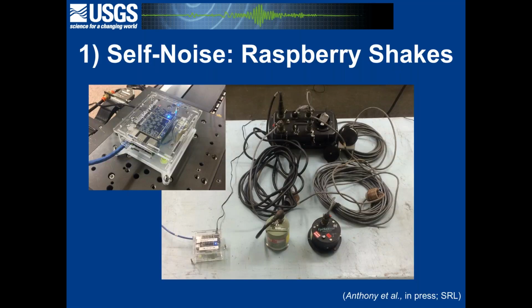Okay, so let's do a quick example of this. I've been thinking about Raspberry Shake seismometers a lot lately, and this right here is a Raspberry Shake. It's a relatively low-cost sensor. This costs about between $500 to $1,000, depending on how you option it. And it consists of a vertical component geophone here, a 3-component MEMS accelerometer, and an integrated digitizer that uses SeedLink. This uses NTP timing off of the internet. So it's kind of an all-in-one unit. You just plug it into an Ethernet connection, give it power, and you can pretty much easily get up and running getting miniSEED data in near real time.